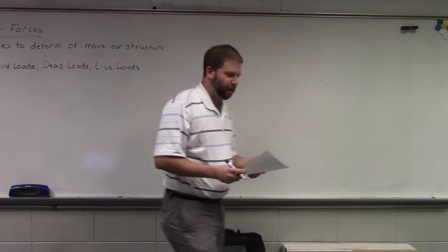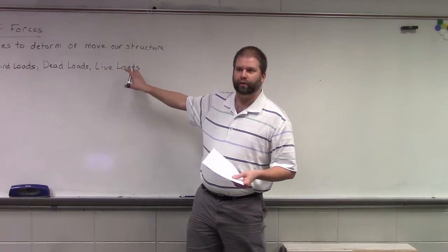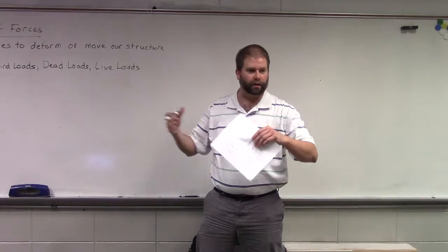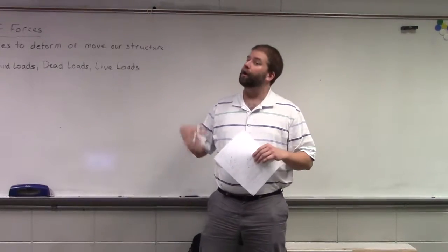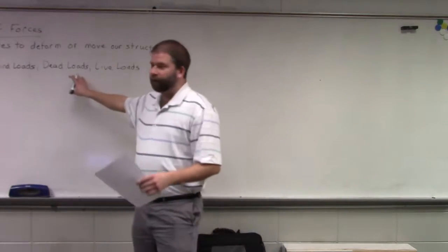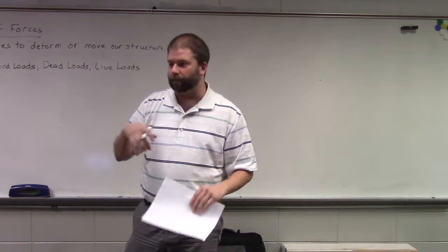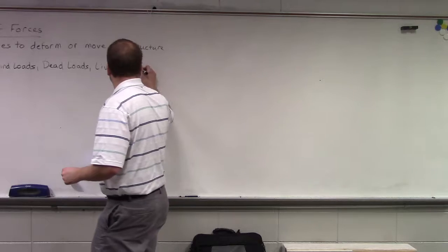So this will be things like, and I remember we talked about it last semester, maybe you remember, maybe you don't, typically speaking, office furniture is going to fall into the category of live loads because we can change the arrangements of our offices, we can change the arrangements of our interior. When we're dealing with things like HVAC, that typically will fall into dead loads, okay? So those are things that once they're put into place, they're staying there, okay? Roof loads, yep.